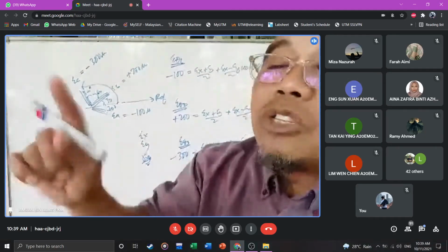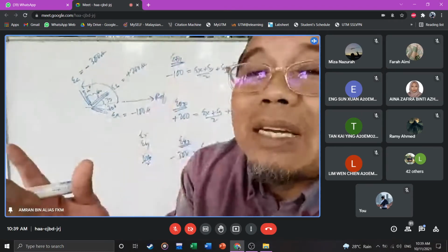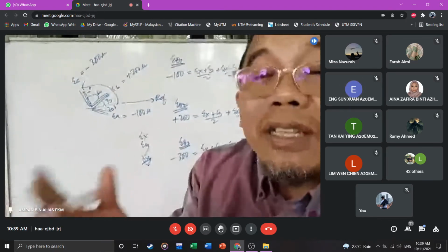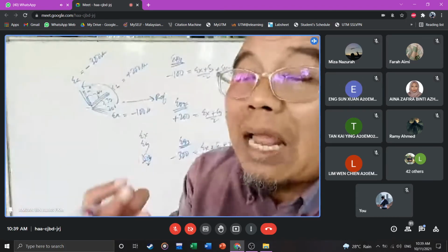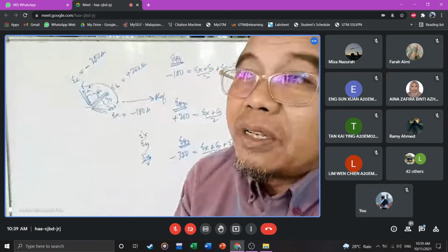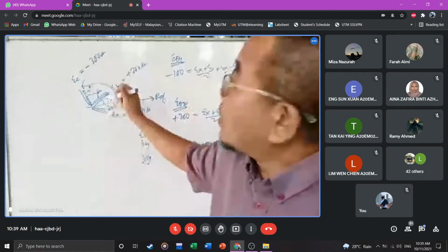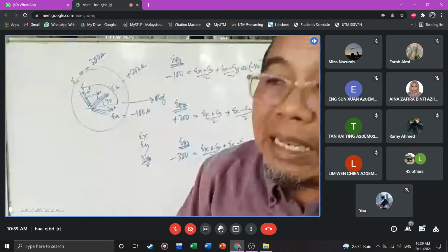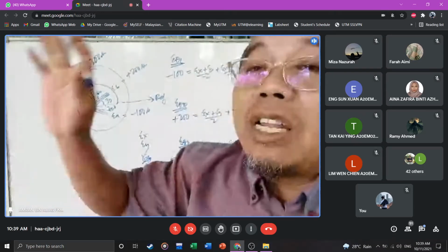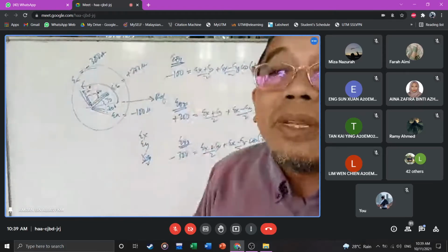But we just took gamma xy for granted. Actually, we don't know how to get the value of gamma; it was just given to you and then you used the equation. So gamma actually comes from solving the equations from the strain gauge measurements. A strain gauge only gives the normal strain, not the shear strain. We solve for the shear strain by solving the equations.